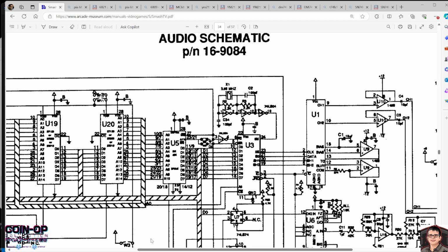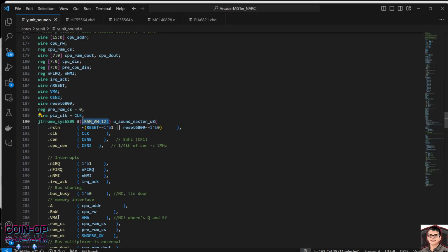When we took a look at this, we found that the addresses go from A0 to A11 right here, and so that's 12. But I think realistically, the game uses only a fraction of that. I think it does not use all 12 addressing bits, or the full RAM width. It just comes with more RAM than it actually uses.